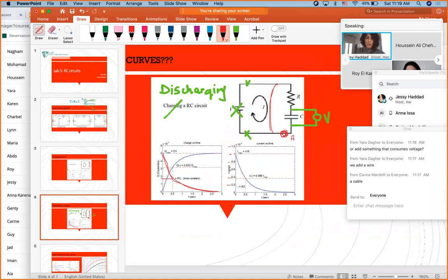All right, so I forgot to discuss the following, that you will be dealing with R1, you will be dealing with R2, you will be dealing with C1 and C2. I will show you the lab report in a moment. So you're gonna pick a combination, R1 with C1, do the experiment, find tau for the charge, then repeat for the discharge.